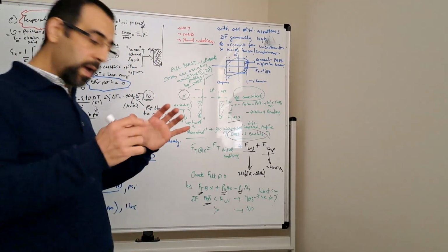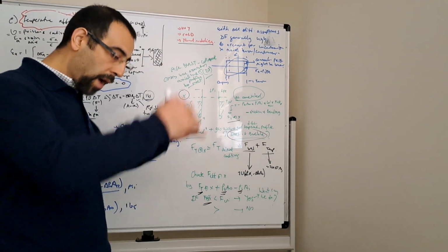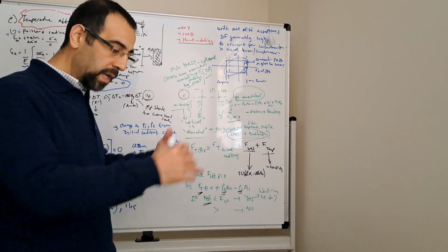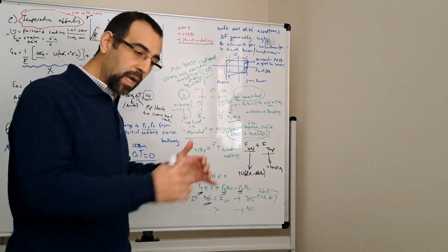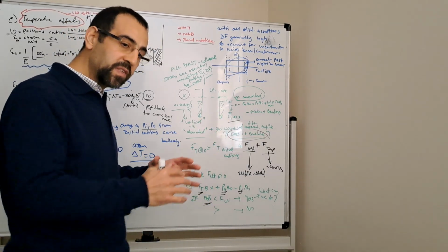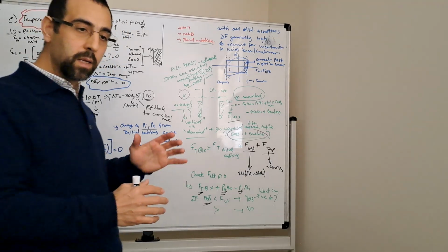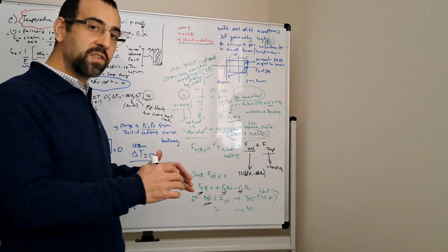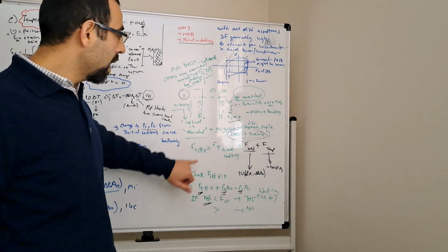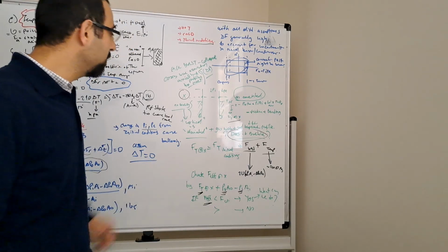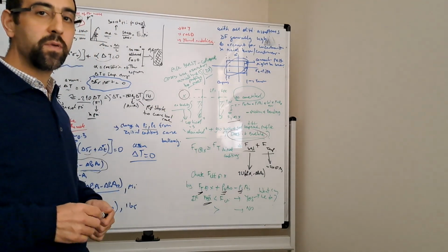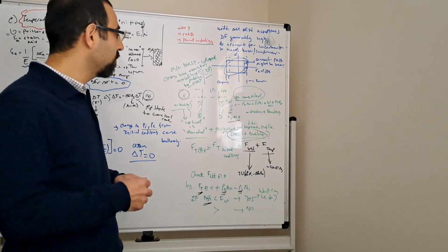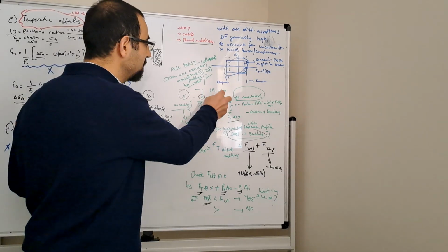On a deviated hole, the pipe is supported by the low side. You have the friction, but there is also an advantage: in a deviated hole, because the pipe is supported, the buckling limit is quite a bit higher, because the wellbore is supporting the pipe. So what else can we do about this? If we are computing the results and we're getting buckling, what can we do? There are a couple of things you can do.